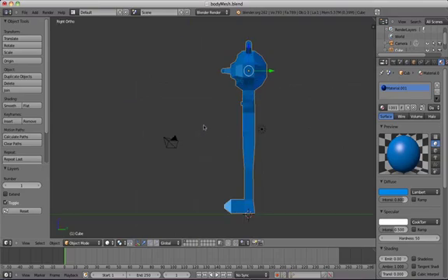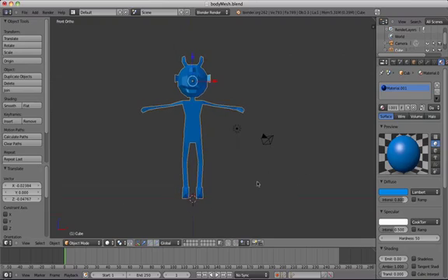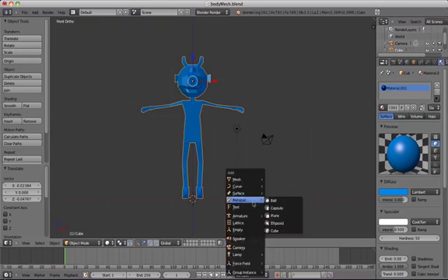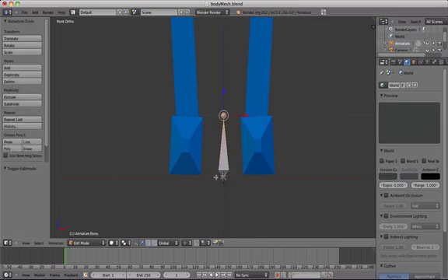So for rigging in this tutorial, it's important that your character is on the x-axis and that the 3D cursor is centered, which you can do by pressing Shift-C. Press Shift-A to add your first bone by selecting Armature, Single Bone. Press Tab with the bone selected to enter edit mode, and you can now see that the bone is made up of 3 different parts. You've got the head, the tail, and the body. Every bone has these 3 sections.